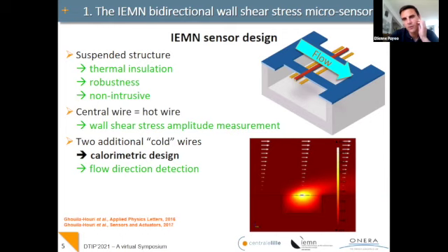And what about when you test your sensor on a real aircraft? The surface can be frozen at high altitude. Do you plan to avoid the influence of ice on your structure? Actually, it's heating. It's heating at about plus 100 degrees. So even if it's freezing at minus 50, let's say, the heater will be at plus 50.